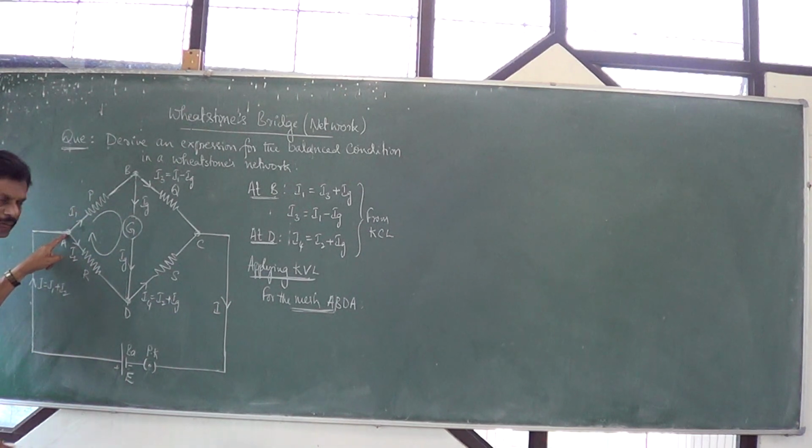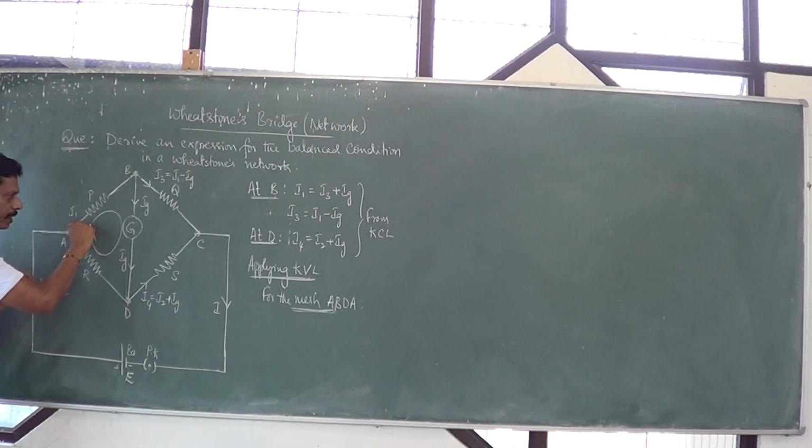Already we know Kirchhoff's second law. I will apply it now like this. Whatever currents are flowing in my direction, I will take as positive. Opposite direction must be taken as negative. See that? I1 in the clockwise direction, positive. IG clockwise, positive. Whereas I2 is coming in the opposite direction, therefore I will take that one as negative.